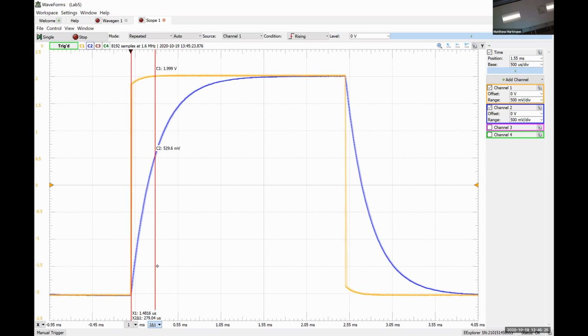So what we're going to do is take A, which was -4 volts, multiply it by a factor of e to the -1, and then add to that B, which was +2 volts, in order to determine what value our capacitor voltage should have at exactly 1 time constant. So take a moment to perform that calculation for me, please, and then tell me what the answer is.